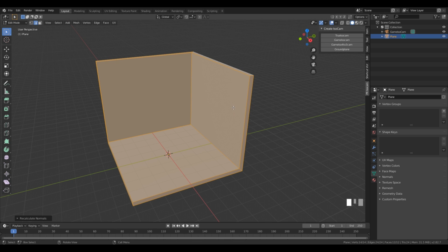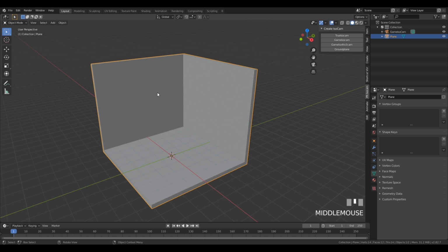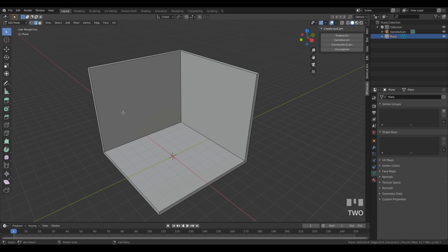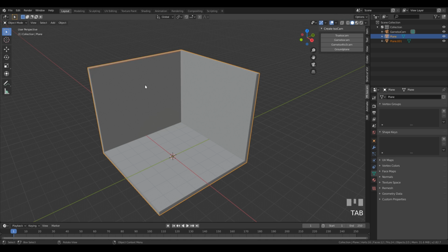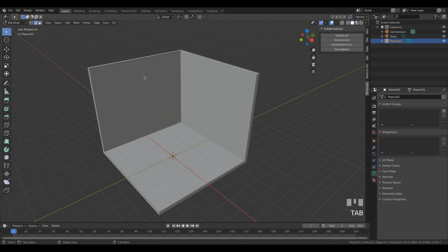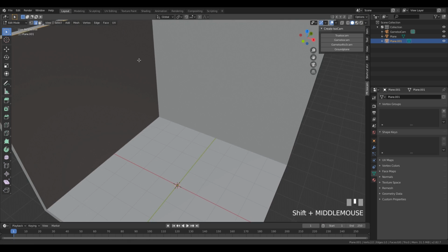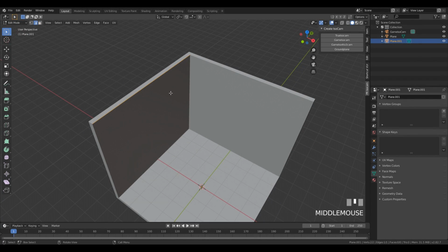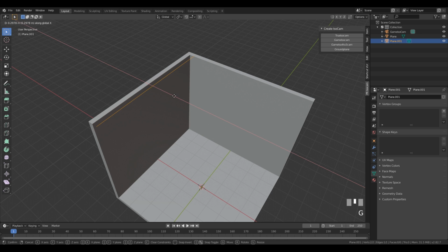Let's step out of this, so press tab to exit edit mode, and we can now create some pipes. I imagine this is some kind of basement room, so let's use one of these edges here. Tab into the edit mode, press 2, select the edge, press Shift D to duplicate, enter P and enter to separate. Right now we can tab out, select the new edge and tab in. And all we need to do is to modify this a little bit, so we can move it further away here. So press G, then X, move it somewhere here.